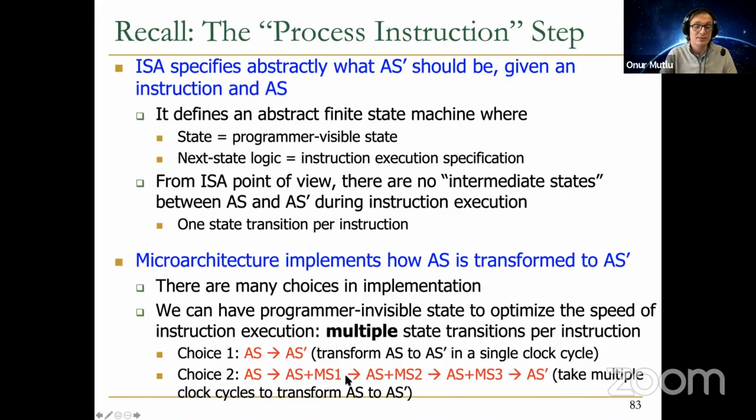And clearly, you can have multiple different ways of doing this for different instructions. So one instruction can take 3 cycles. Another instruction can take 1,000 cycles if it requires 1,000 cycles. And this is important, again, because now those 2 instructions can be optimized completely independently of each other. If the common case is the instruction that takes 3 cycles, you focus on that.